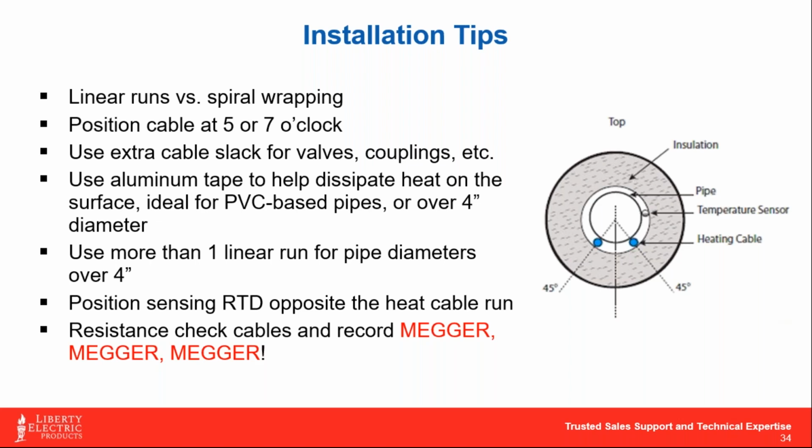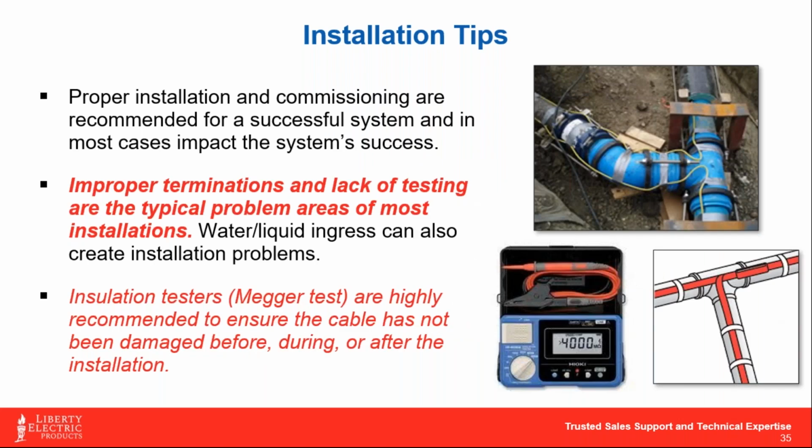So the biggest thing when we're talking about installation is Megger testing. Basically every heat cable manufacturer is going to require that you use Megger testing for warranty purposes, but that's the easiest way to ensure the cable wasn't damaged during installation. And for those of you folks that are not familiar with what a Megger tester is, it's similar to a multimeter, but we're not checking current and voltage value. All we're checking actually is the insulation value of the jacketing on that cable. So when we send a test charge through it, if there's a cut in that jacketing or a leak to ground, this tool is going to show us that.